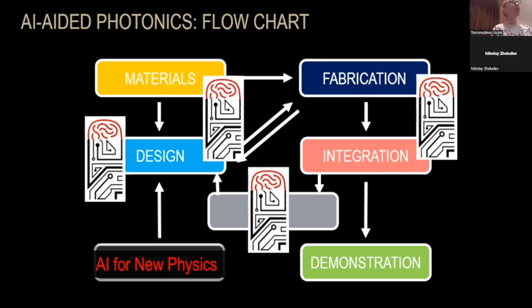And the second part, for emitters, is experimental. For example, we had about 100 emitters, and we used 20 emitters to train our classifier. How it is done: you do both the long measurements and the short measurements on all 20 emitters, and you know the ground truth, whether each one is good or bad. This is how the classifier is trained. Then you can use this classifier on the remaining 80 emitters to do just 1 second measurements. So we tested it experimentally. The same for the imaging as well, that it gives you a higher resolution.